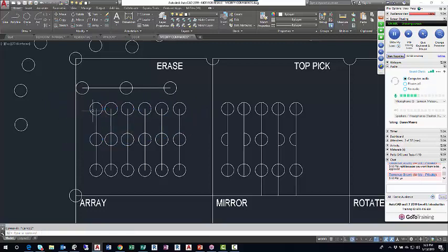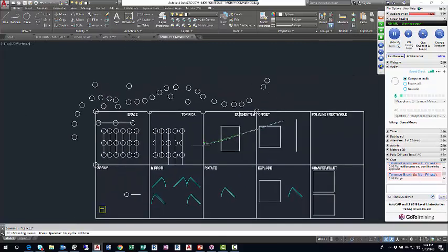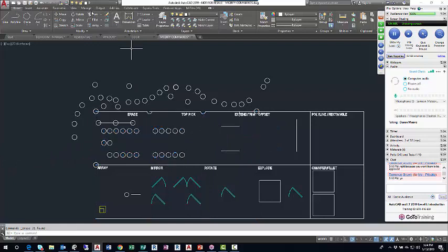Oh, I got that one. I was trying to come in just short of it. Click and hold, move from right to left, like so. So I just got the top row. Click and hold, left to right. Now, the reverse of that is click and hold and move from right to left. This is the crossing lasso. And again, it's much more aggressive. Anything it totally encloses or simply touches is selected. So I want to get all those lines, boom. Very destructive.